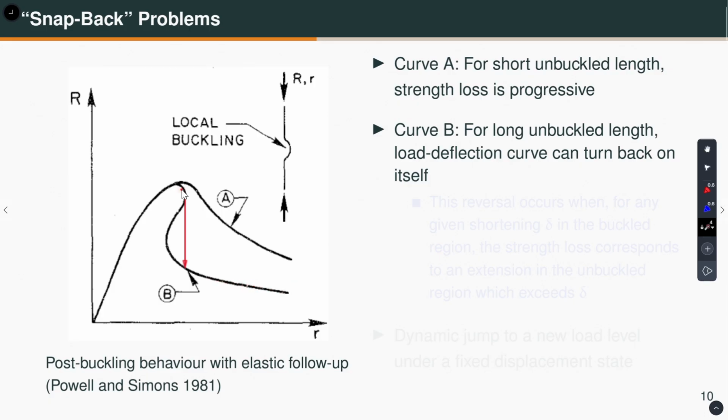But why is this happening? Why is the force displacement curve turning back? Let us discuss. When buckling happens, there is a drop in the capacity. The moment there is a drop in the capacity, the portion which is remaining elastic has to unload elastically. It was earlier compressed, now it should extend. So, these two portions are extending and this is compressing.